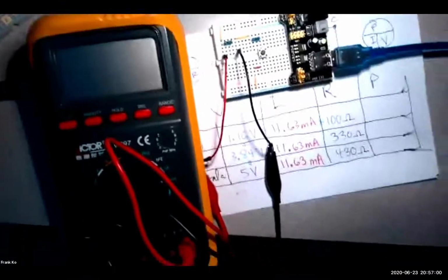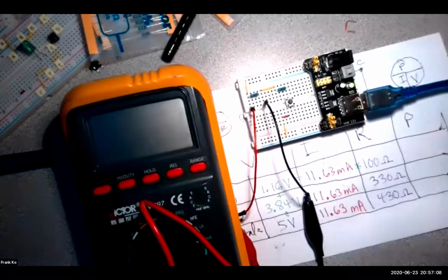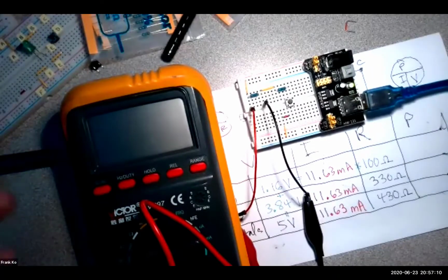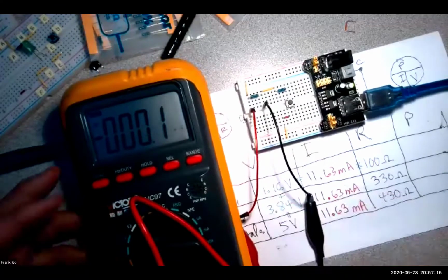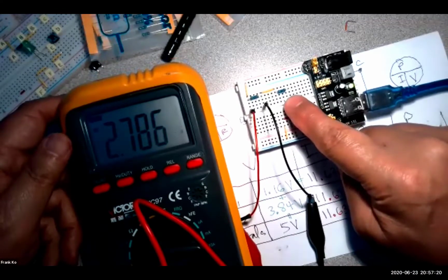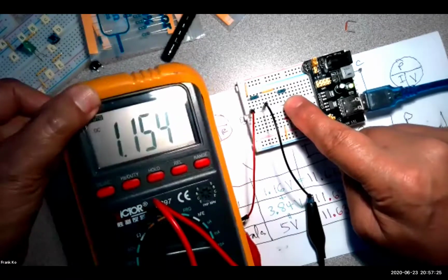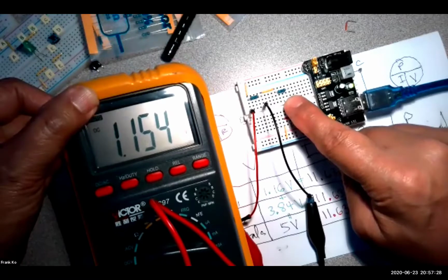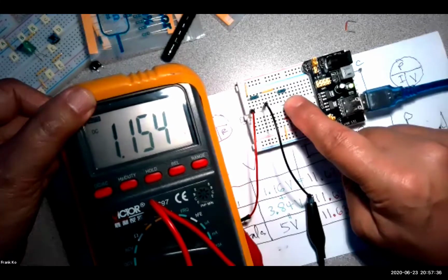Let me raise this up a little bit further so we can have a better view. Refocus. It is now refocused. Change my angle of light and turn the meter on for DC voltage. We expected 1.16 volts. If I energize the circuit by pushing the switch, do I have something close to 1.16 volts? I do.